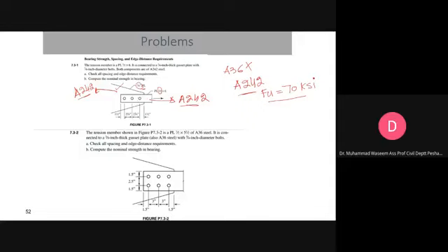Okay. Now center to center distance is given. This Le is given. Okay. And this time you have to use 7/8 inch diameter bolts. Okay. Now you have to check the spacing, edge distance requirement, and the nominal bearing strength.